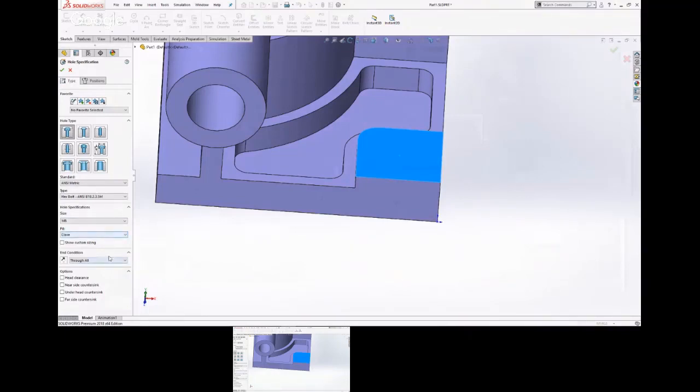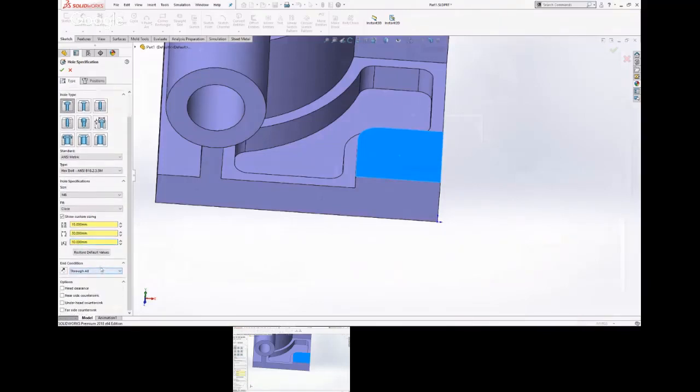So close fit. And then you can actually check the custom sizing. So, the through hole diameter. On mine, I'm referencing a toolbox that I used to use at the mold shop. We used different type bolts, so we had our own custom sizing. So mine are always wrong on here because we changed it. I've carried that toolbox with me for years, and that's why it is. So the through hole diameter is going to be 15, and the counterbore diameter is 30. Then the counterbore depth is 10, and the end condition is through all. So there's my settings in there.